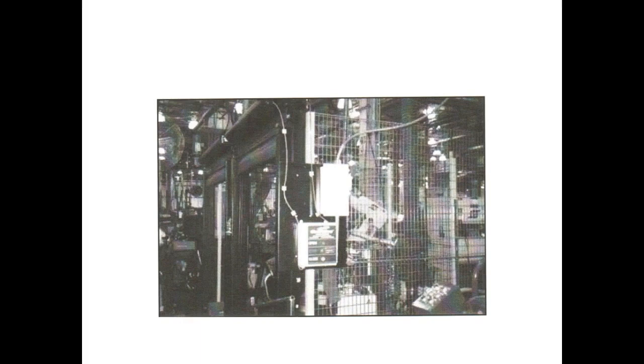So these safety devices, if you step on a mat, the robot can stop, right? They usually stop. When you step on these safeguard devices, the robot does not brake. It does what? Stop. It doesn't decelerate. Stop. Then you step off the mat. Then how do you start the program going?